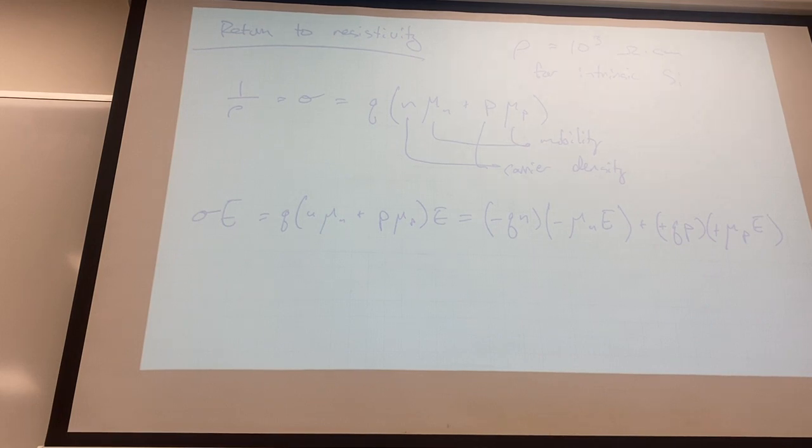Now we've got things grouped in charge density, that's in units of coulombs per cubic centimeter, and velocity, like we showed earlier, centimeters per second. Charge density times the velocity ends up being something like current. It's current density instead of just current. That equals what we abbreviate as J, which is not the square root of -1 in this case. This is current density, amps per square centimeter, the number of amps per unit surface area flowing through a two-dimensional surface.